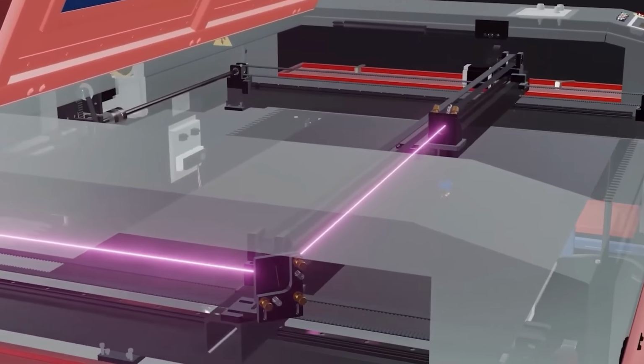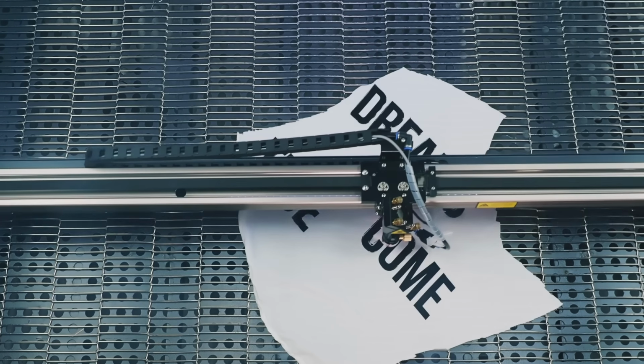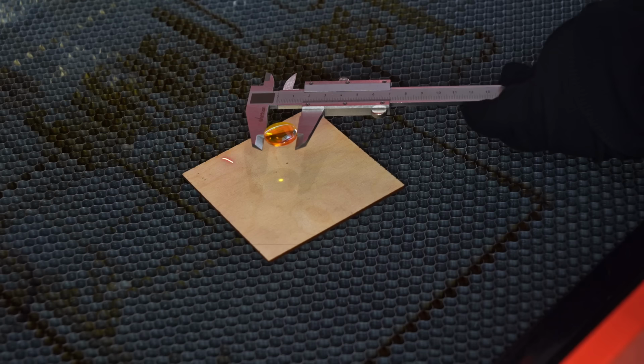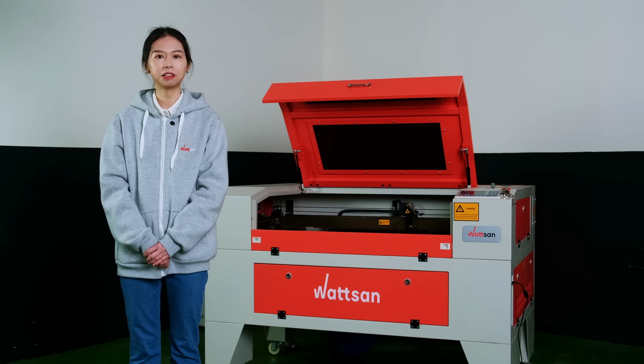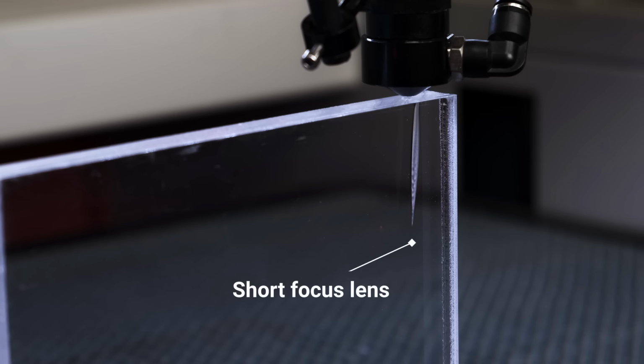When the laser beam passes through the lens, it converges to a single point. It focuses. At this point, the beam reaches its smallest diameter on a focal dot, after which the laser starts to diverge again. A critical parameter here is the caustic zone, the length of the section along the beam's axis, while the beam diameter remains close to its minimum value.